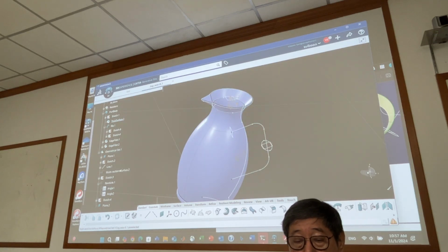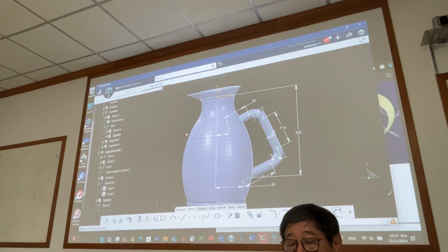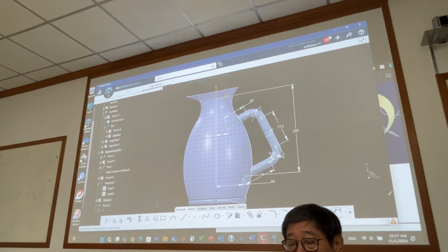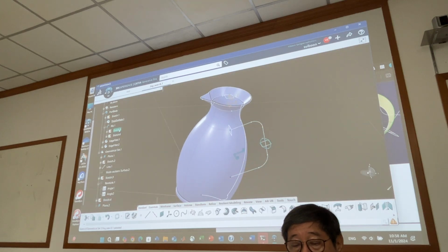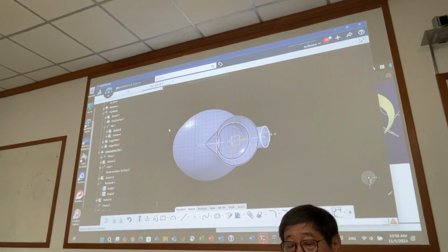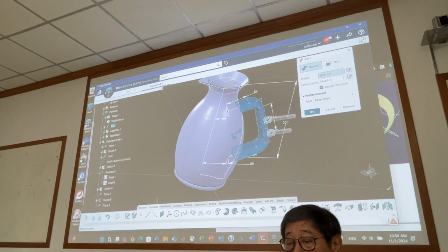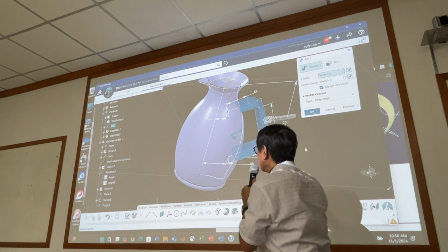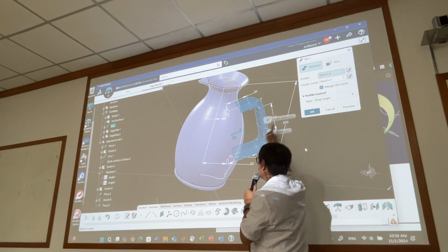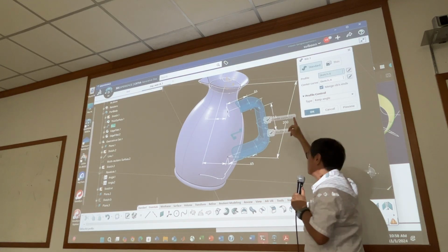You create this rib command, you see, you have this one. Cross section, the other one cross section, right? This one cross section, this one, see? You got the rib command, you use merge rib end. Don't forget, when you use rib, I give it only up to this edge, so merge rib end, merge rib end.